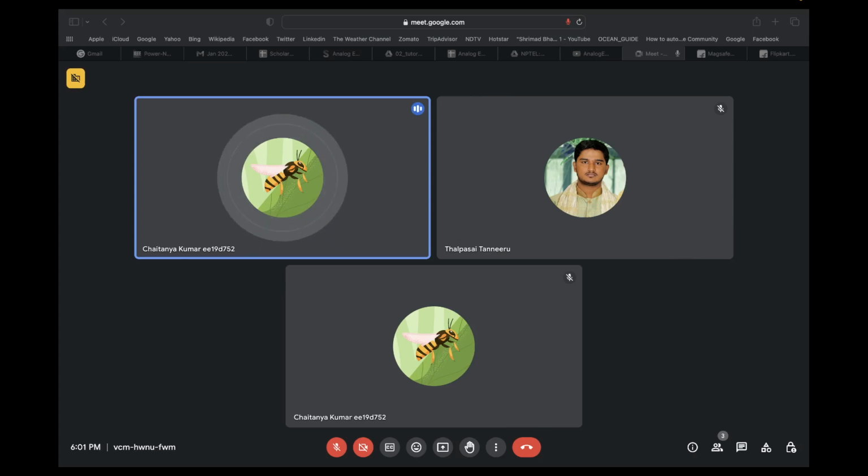In tutorial 2, the common source amplifier made with a MOSFET was discussed. First of all, its large signal parameters were discussed. Then we shifted to small signal parameters and determined the gain of the MOSFET. We looked at the regions of operation of the MOSFET, and then at various biasing techniques. We looked at the simple resistive divider bias, and after that some robust techniques which can prevent the gain variation across process, voltage and temperature.